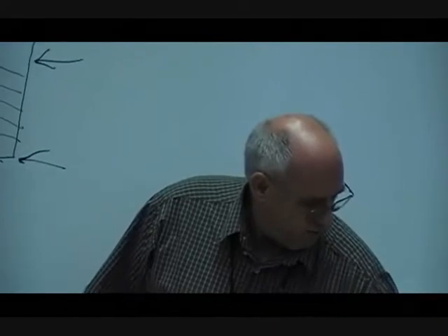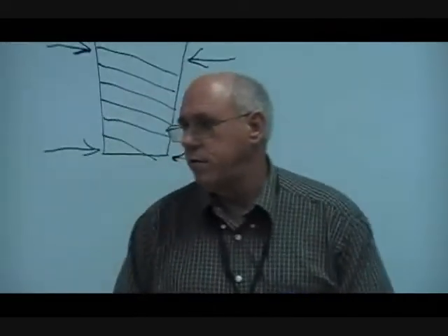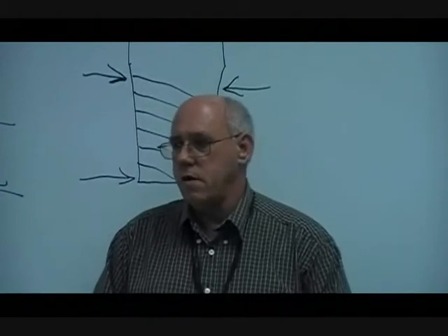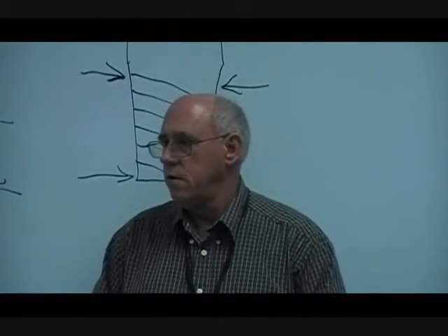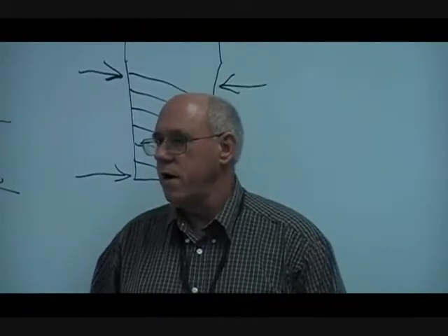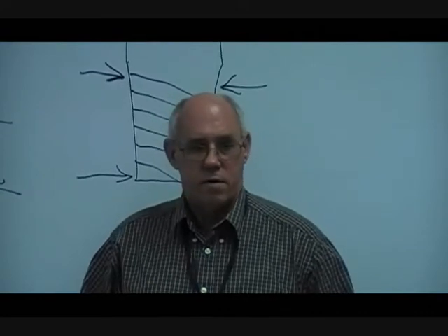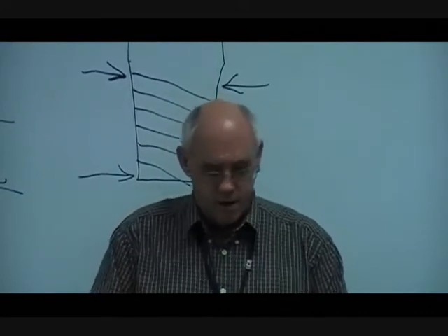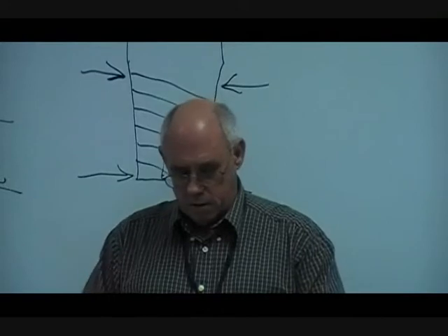I think it's time we move into copper. Copper, and we're going to be talking about mechanical joints. What's the difference between mechanical joints and sweat joints? Sweat is usually brazed or soldered. Okay, mechanical includes flare, includes compression.